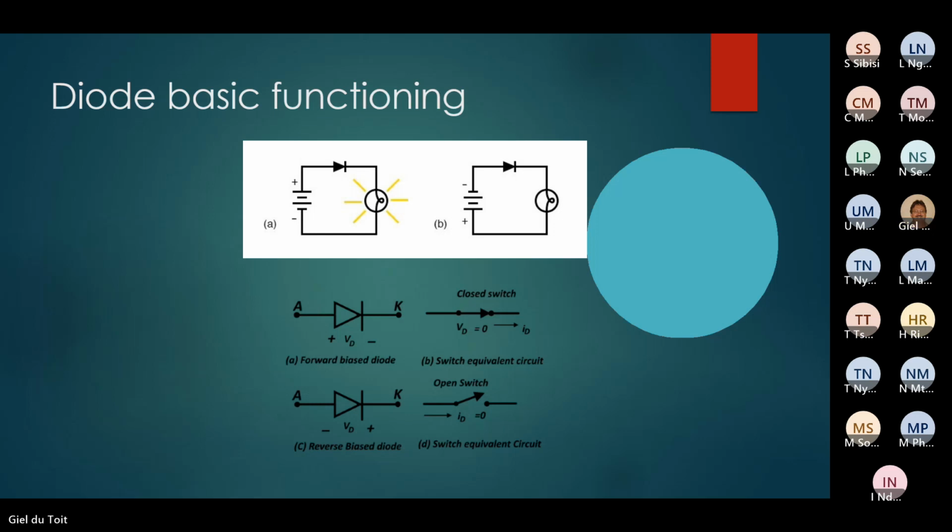However, when current tries to flow in this direction, it's reverse biased. So in forward biasing, it's always the normal current through the diode, but in reverse biasing, the current is very small, much smaller than forward biasing. The diode cannot take a lot of current during reverse biasing, only a few, like microamperes. The only diodes that actually work with reverse biasing are zener diodes, and a few others, we'll get to them.